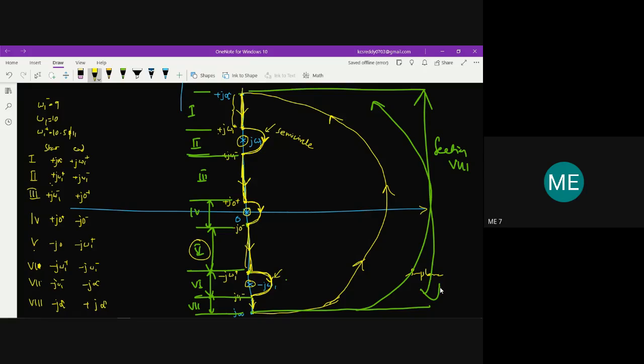Now the mapping of these sections, all these 8 sections which I have discussed here, has to be mapped in the F plane. How are we going to achieve this? Because this is the S plane, you need to use the mapping theorem and convert all these S points into points on the F plane. Then we have to get the Nyquist plot.